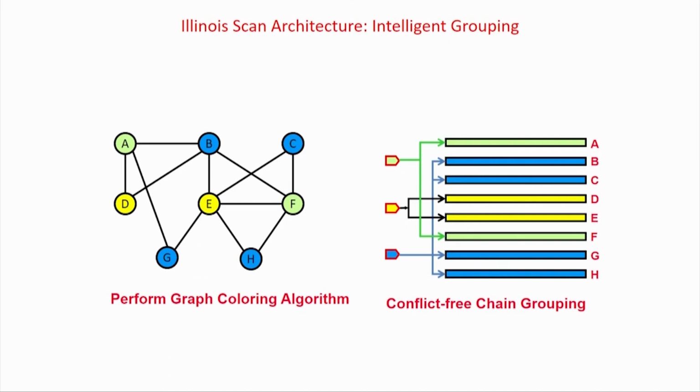So therefore, a lot of research has been devoted to finding out how we can optimize scan chains, as well as reduce the test application time and not make any test faults untestable. The Illinois scan architecture is one of the most prominent architectures for that, which we have mainly discussed in this lecture, along with partial scan and Illinois scan.